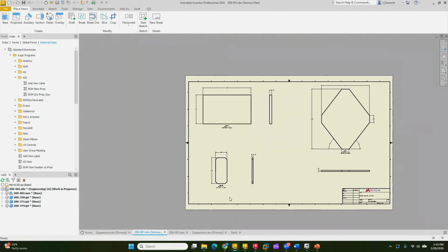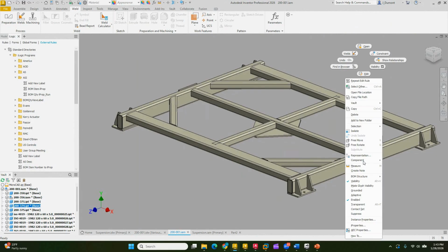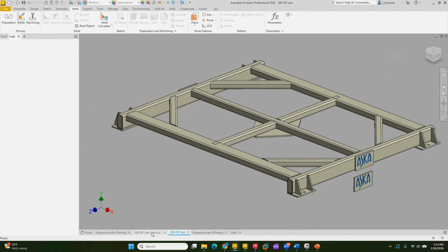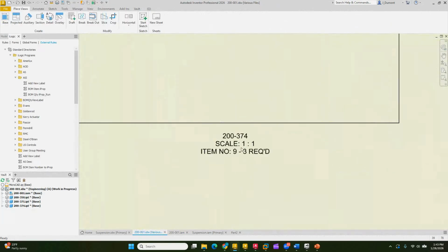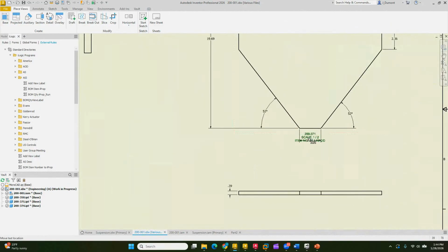And if I make a change to the assembly file, this is kind of a silly change, but I'm just going to do a copy and paste. Now I have 3. I just run the rule again, and it's done, and the drawing updates. I never have to worry about it. I never have to think about it. I just run it. If I add another view, I just run the labels again, and I'm done. It puts it on the base, every base view will get that label.